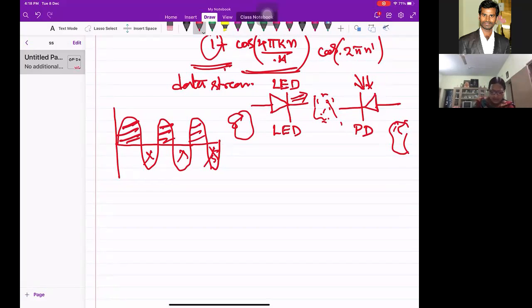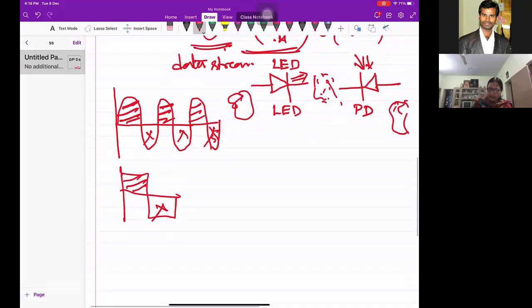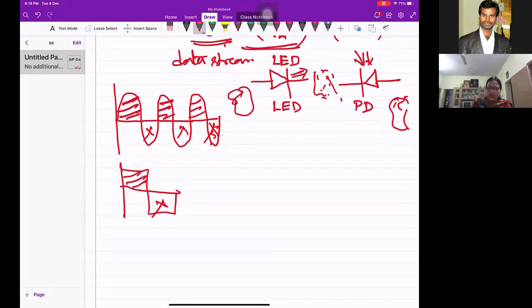At least not a sine, I am sending a rectangular pulse. So it will allow only positive, but it cannot allow negative. Then what is the other alternative? When I am passing the signal through the LED, a sine wave is connected through the LED through some biasing. It allows this current and this light falls on the photodiode. The photodiode will give you the output in the form of your half-wave rectified waveform.